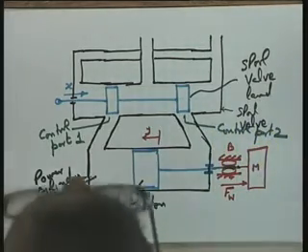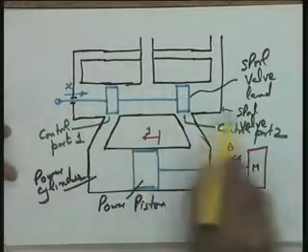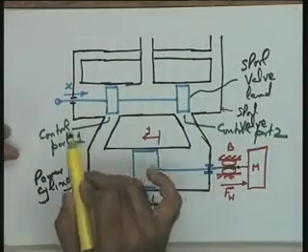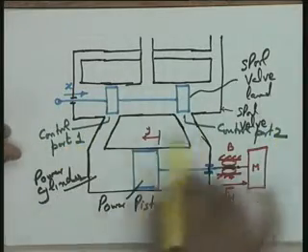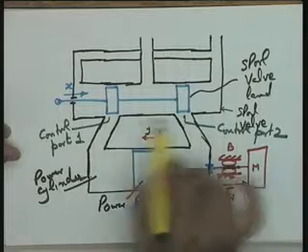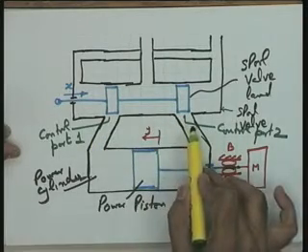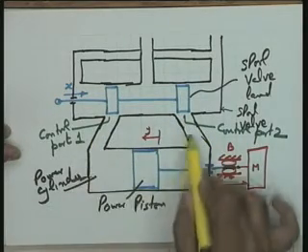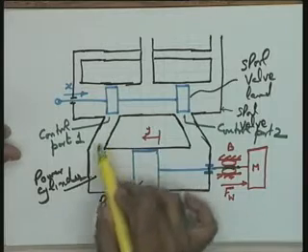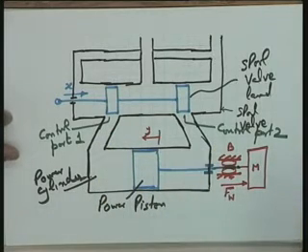These are the two control ports. This spool valve movement covers or uncovers these two control ports, and the movement of the spool should be very clear now. It controls the flow of hydraulic fluid in this particular power cylinder. From where is the hydraulic fluid coming?